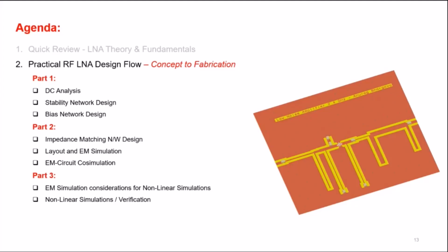It's not that difficult. But let me tell you, wire bonding is going to be your bottleneck, because any bond wire is like an inductor. But we do have some clever compensation techniques to decrease the impact of wire bonding. For example, you can put multiple wire bonds in parallel to reduce effective inductance. You can make the launch pad of the bond wire capacitive in nature so that you can increase the bandwidth. So there are some options available, so consult with the local team.